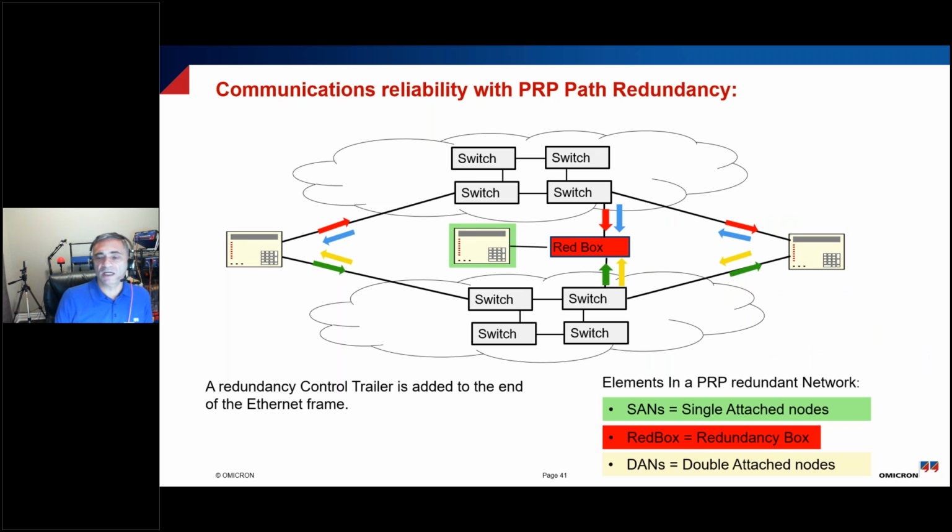And in order to do that and to make sure it's robust, since we saved all that money on copper cables, we put in redundant communication links. So here's an individual relay over here, and it has two fiber optic Ethernet connections, one to one network and one to a second network. And all the other devices are connected up to both of these networks. So if there's ever a problem with one of these networks, the device is connected up on the second network, and messages are sent out on both networks at the same time. So if one network has a small problem, the message gets through on the other network to the other side.